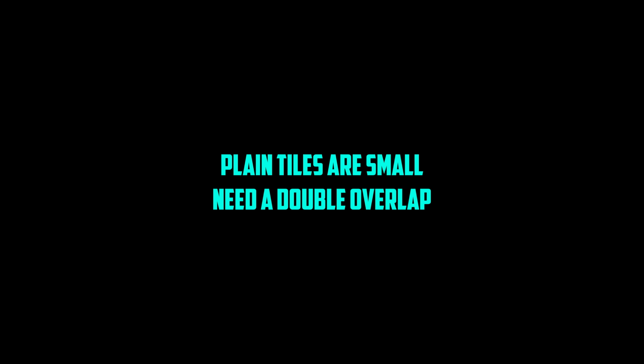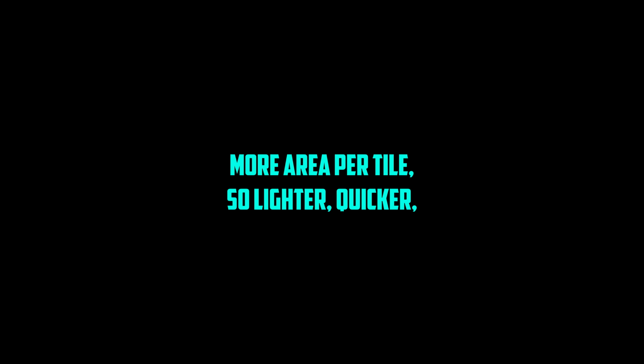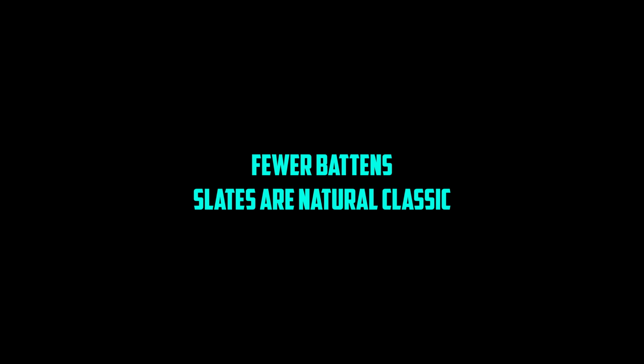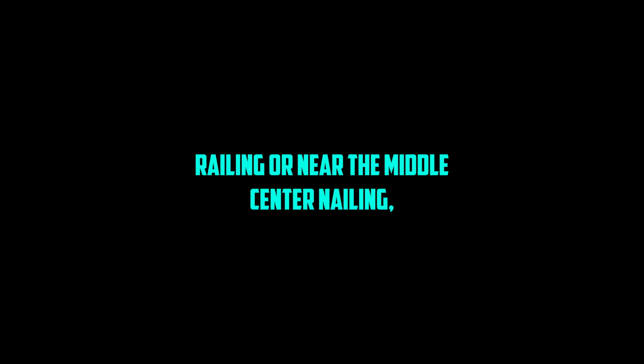Tile types. Plain versus single lap. Plain tiles are small, need a double overlap, so more tiles, more battens, more labor. Single lap tiles are larger, often interlocking, cover more area per tile, so lighter, quicker, fewer battens. Slates are a natural classic. Beautiful, durable material, split thin, used on pitches usually over 25 degrees, laid with a double lap like plain tiles, fixed with nails either near the top, head nailing, or near the middle, center nailing, depending on slate size and exposure, to stop them rattling or lifting in wind.